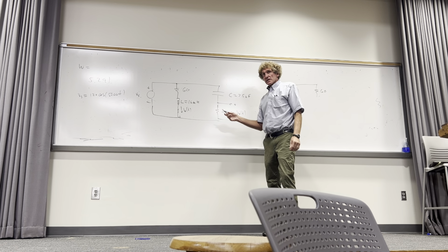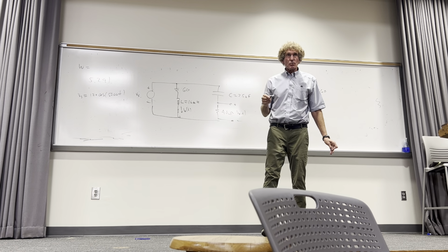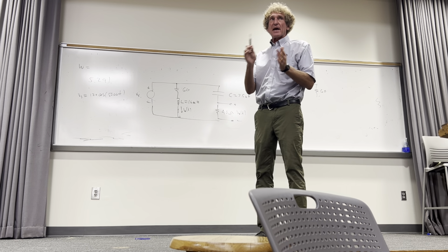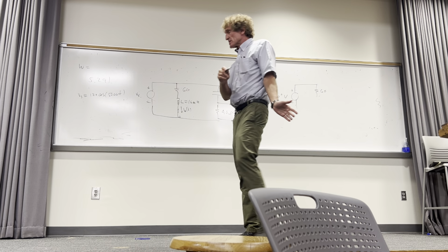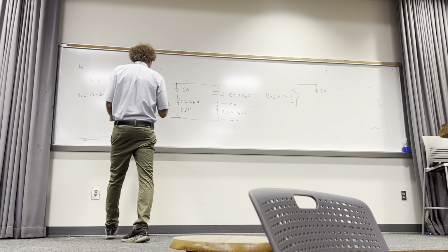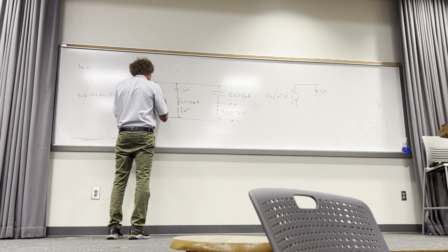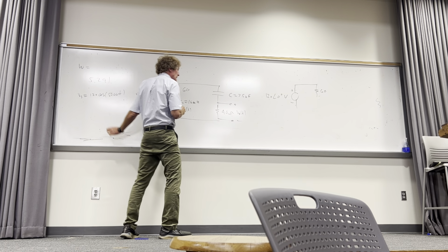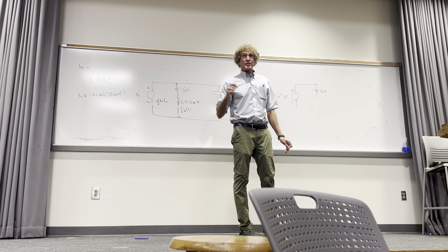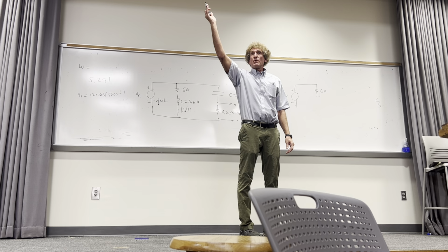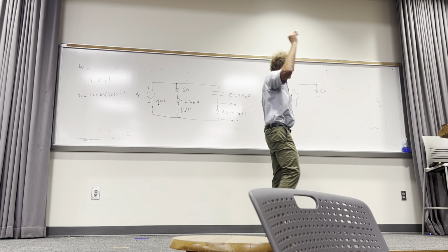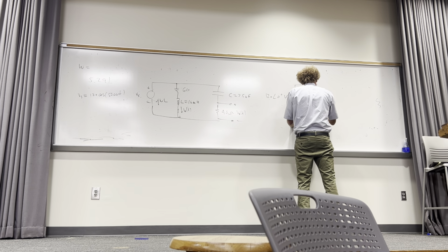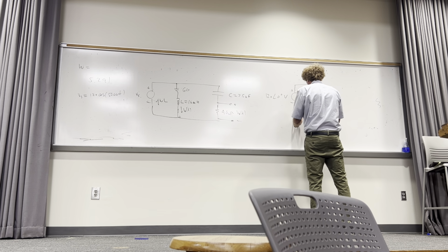Now, instead of 16 millihenries, we have to put the equivalent phasor impedance. Everybody follow me on this. The complex impedance. And for an inductor, the impedance would be j omega L. That omega is 5,000. Do you all agree with that? If you do, raise your hand so I know who I'm talking to. Everybody must see this. It's critical. So I'm going to come down here and somebody's going to give me that value.